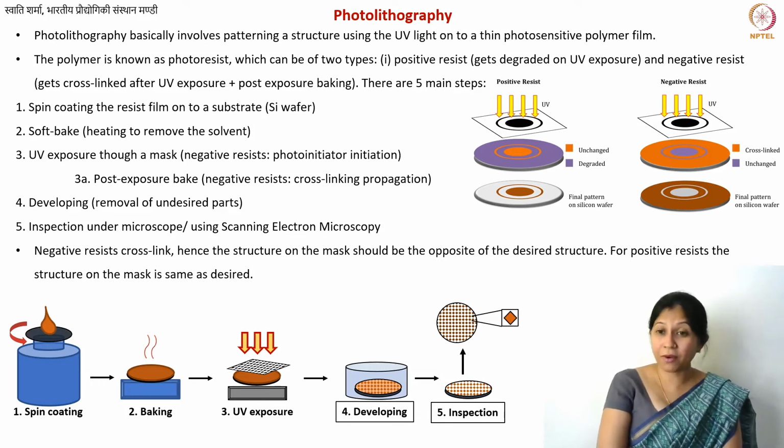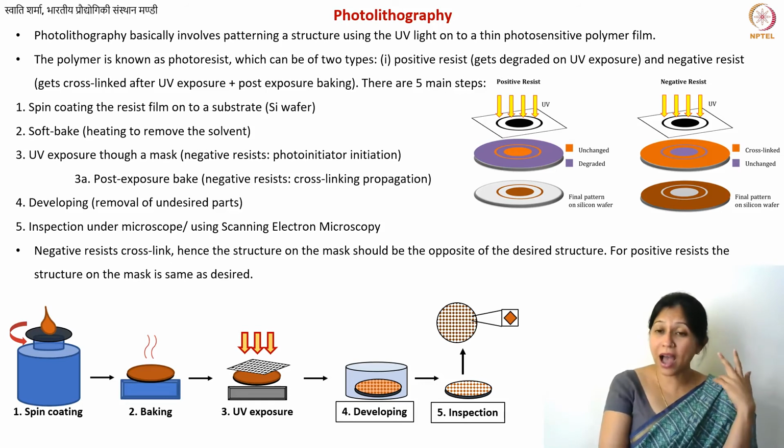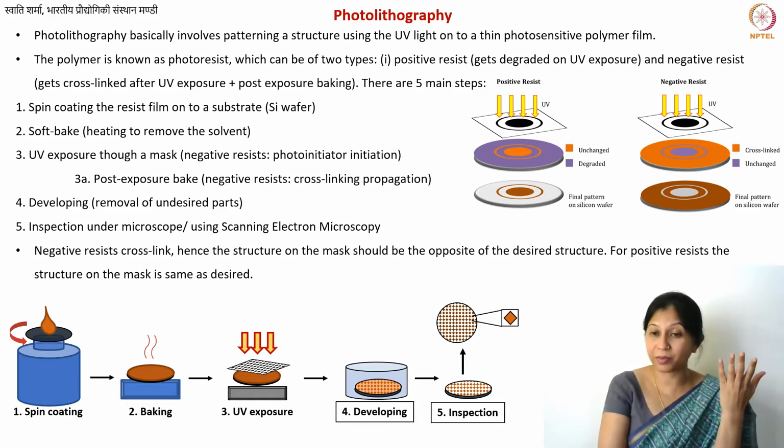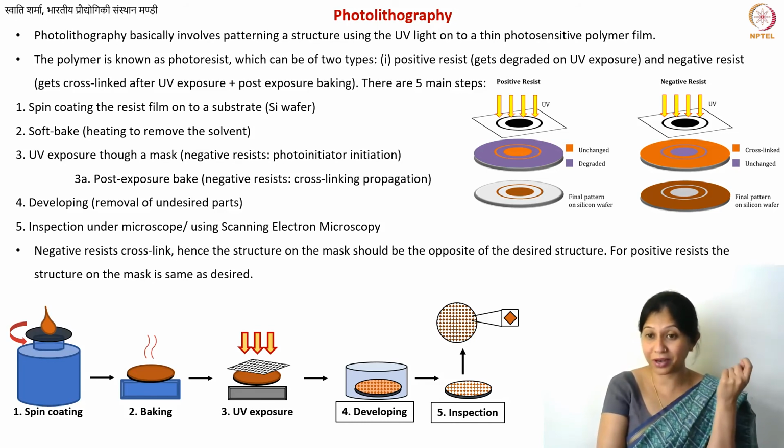When you're performing this heat treatment operation, you are heating it very slowly, at lower than 5 degrees centigrade per minute. That's your ramp rate. So this process goes on for several hours, and when you reach the highest pyrolysis or carbonization temperature, 900 for example, you would keep your material at 900 for at least an hour.